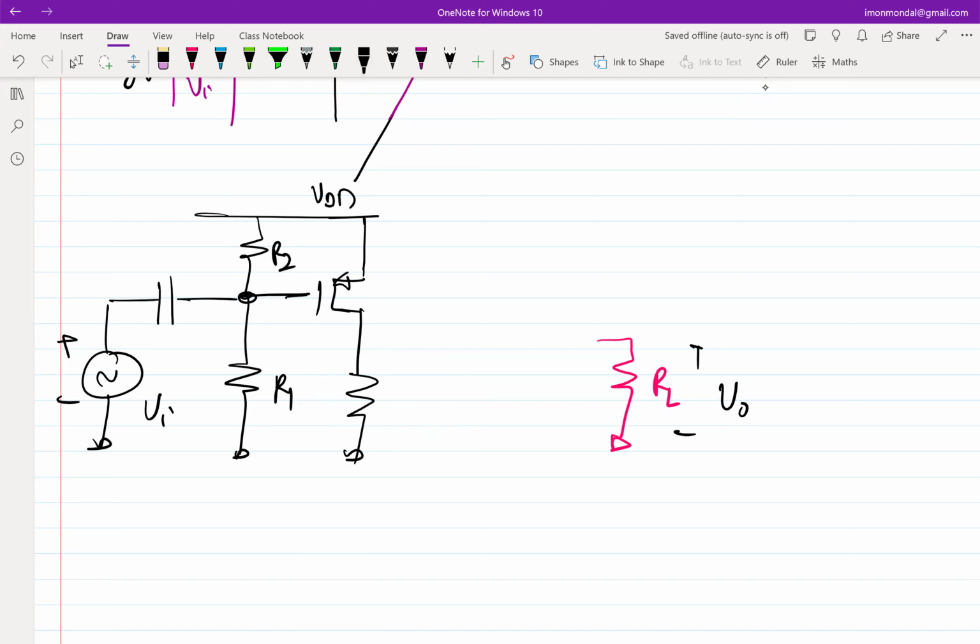Okay. So firstly, we need this one, because let me now call this RD connected to the drain. We need this one because if we don't have that one, there is no way I can pass this entire small signal current into the RL. So we have to connect something here so that the signal current that flows through the device M1 goes into the RL.